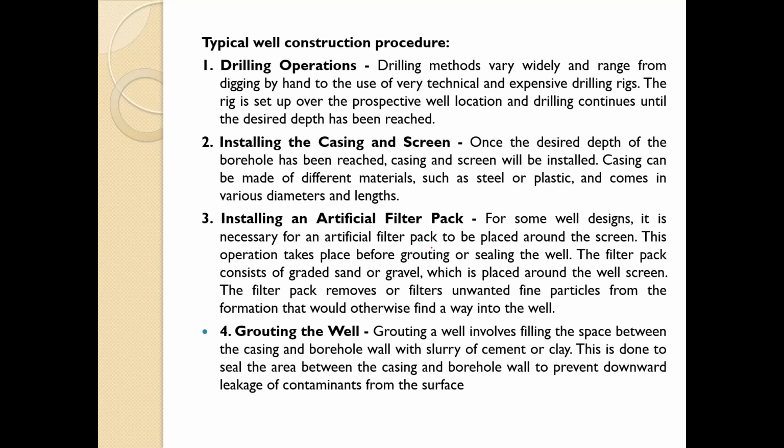And last is grouting the well. Grouting the well involves filling the space between the casing and the borehole wall with a slurry of cement or clay. This is done to seal the area between the casing and borehole wall to prevent downward leakage of contaminants from the surface.